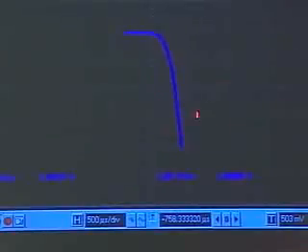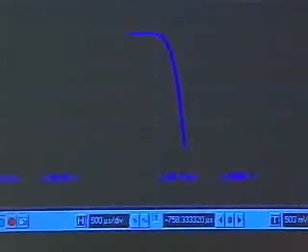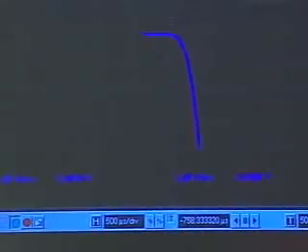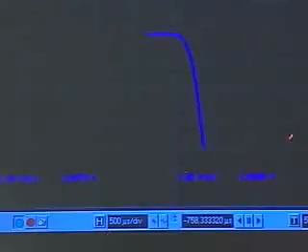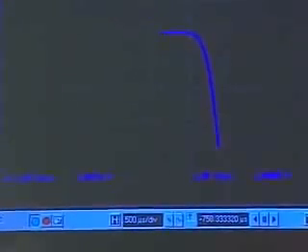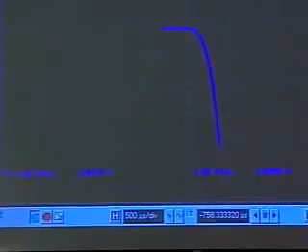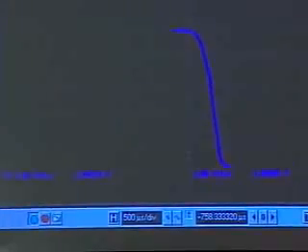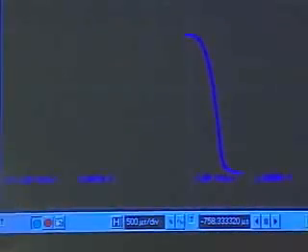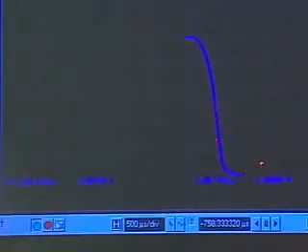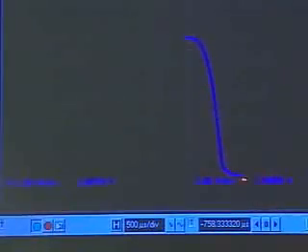And at some point here, this begins to go into its triode region. What I'm going to do is simply increase the input voltage Vi, and you will see the output keeps dropping. And as you can see, the output begins to go into a space where the gain is no longer more than 1.